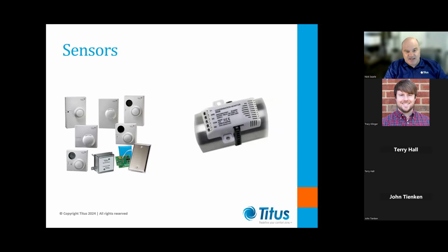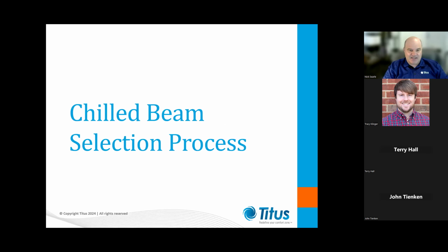But these type of sensors, I mentioned those just a little earlier. They're not really required. They tend to be too sensitive, and for several buildings I know of, certainly in the early designs, they actually had to rip them out because they were just so sensitive. Because it's normal to expect a slight bit of misting on the chilled beam supply coil. So strapping these to each chill beam is going to add a lot to the cost of the system, and quite frankly, they're unnecessary.